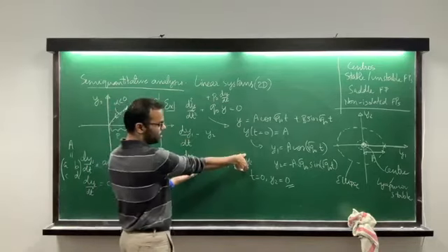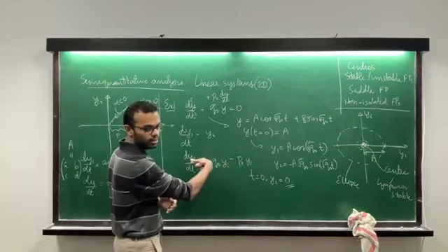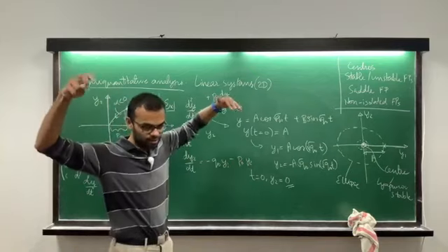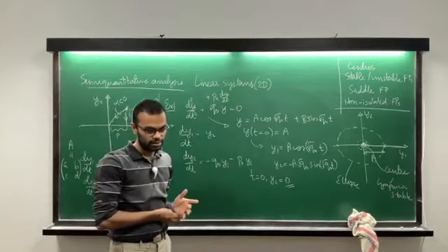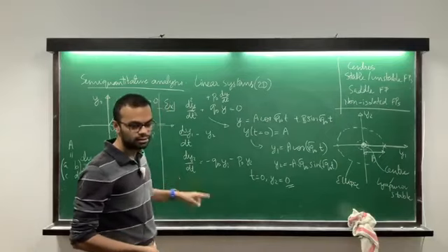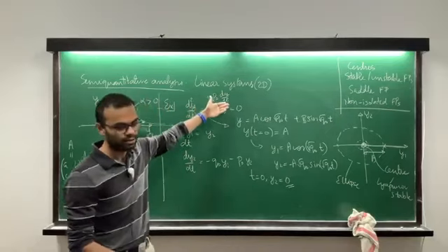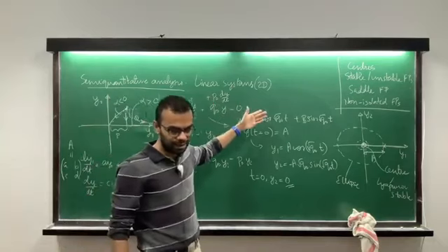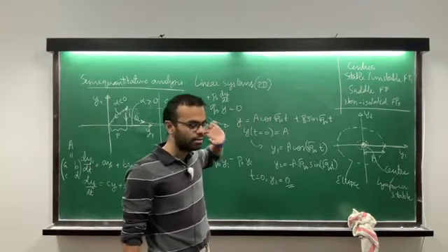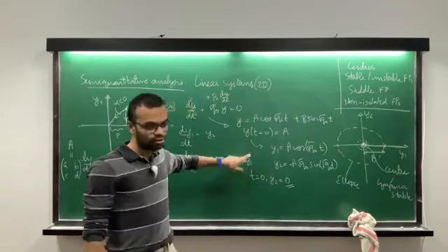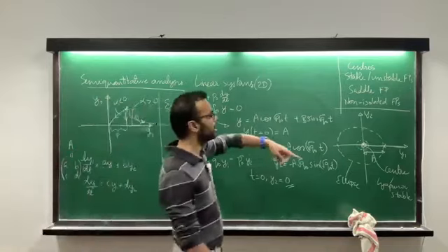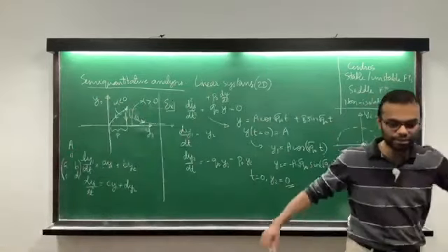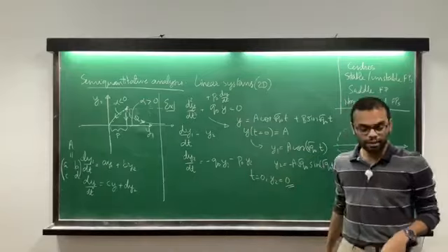This term in this 1D equation is going to act like exponential minus t. If you solve this, this is the spring mass damper equation, which you've probably seen again. This term is going to serve to dampen it, making exponential minus something times t, something depending on q naught and p naught.